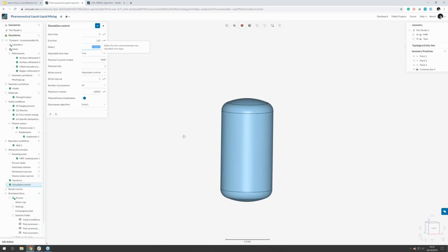If you're familiar with running transient simulations, you tend to get the instabilities at the beginning of your simulation. If you pass through the first 5% of your simulation, you're probably in a good place. So it's all about getting that initial stability, and then after that you're probably going to be fine.